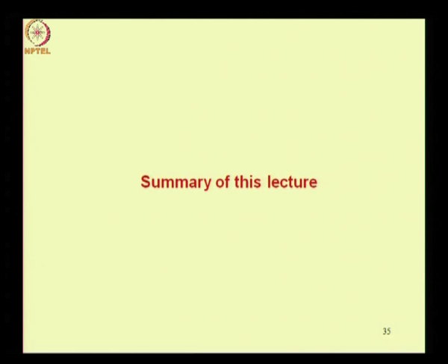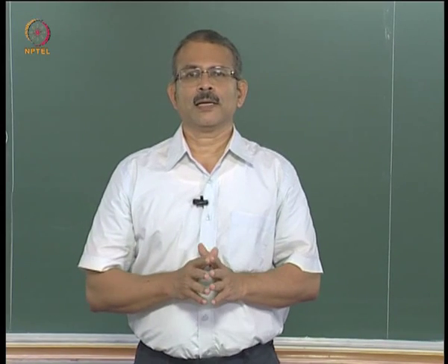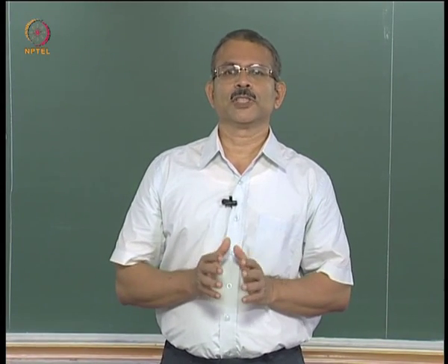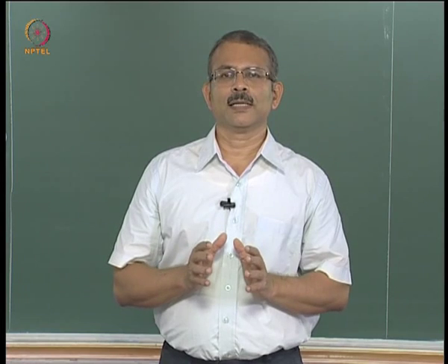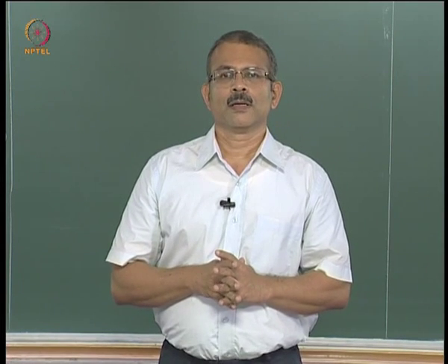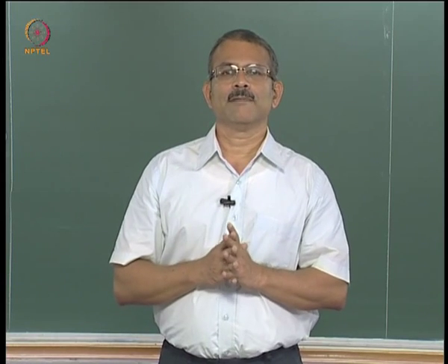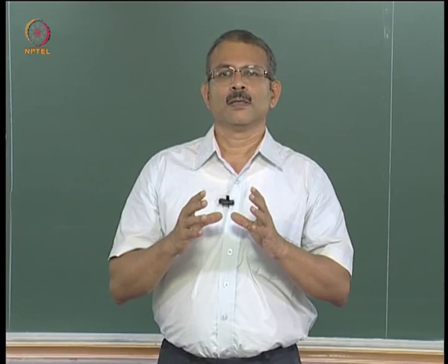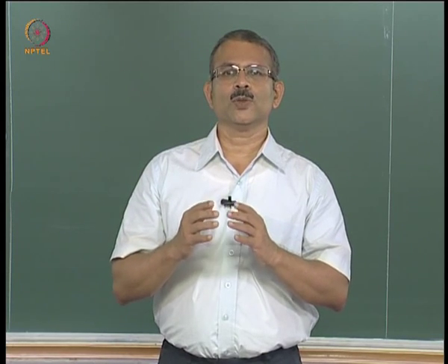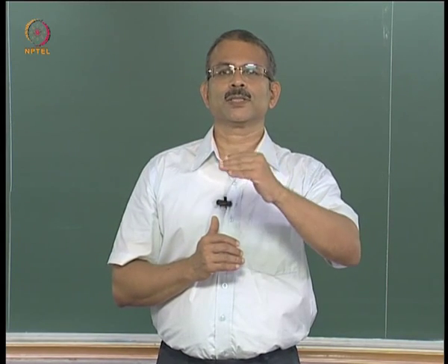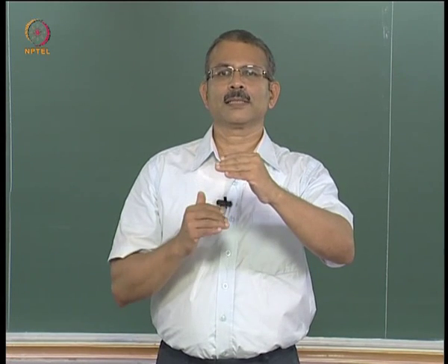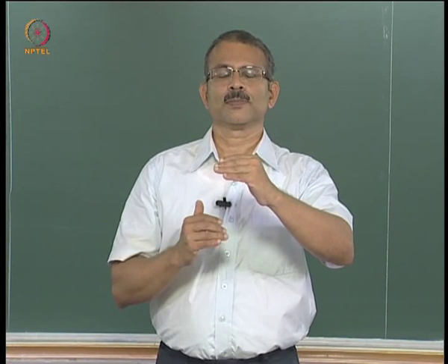So towards the end of this lecture, let us make a summary of the key points. So in this lecture we started discussion of the equations which should be solved to derive the current in a semiconductor device. So we discussed the organization of these equations, and we said that you can separate these equations into two sets. One set is the equations of electromagnetic field and the other set is the equations of transport.